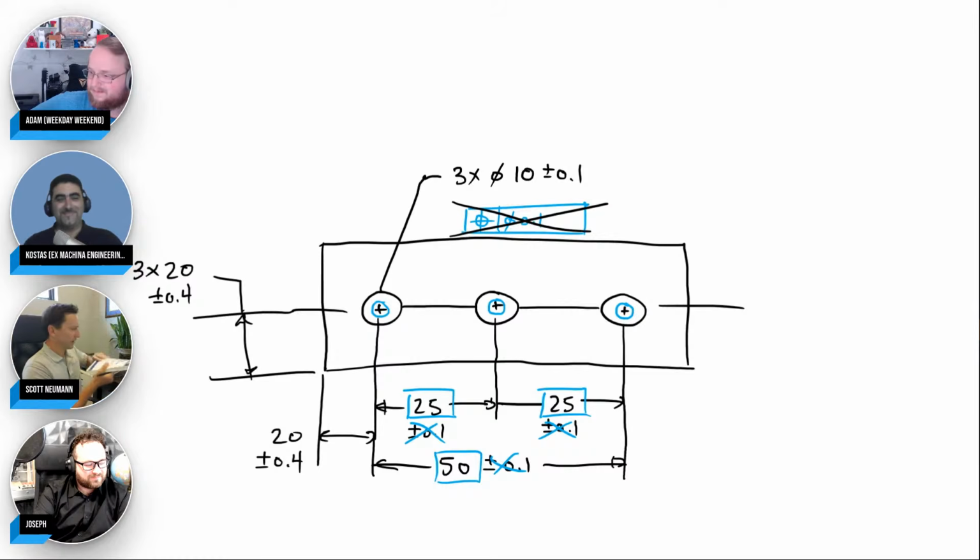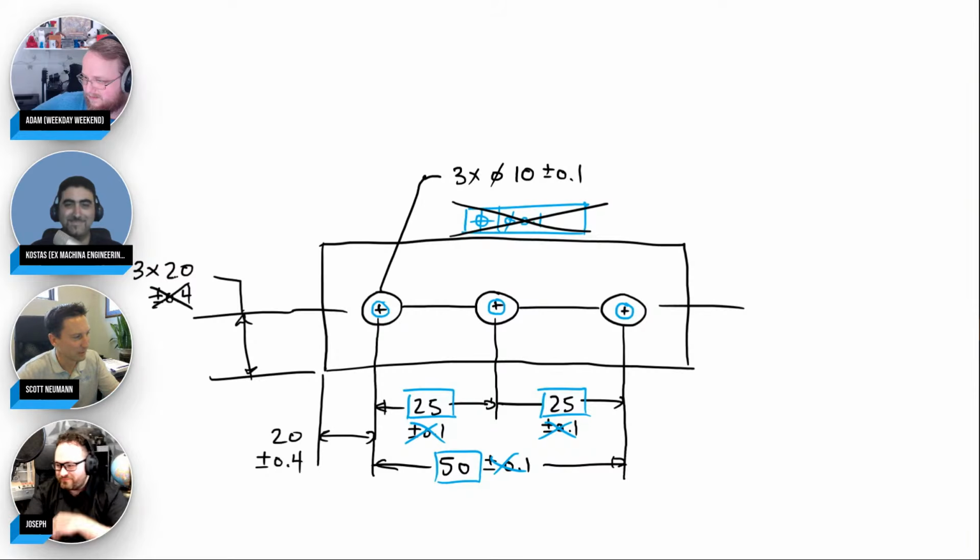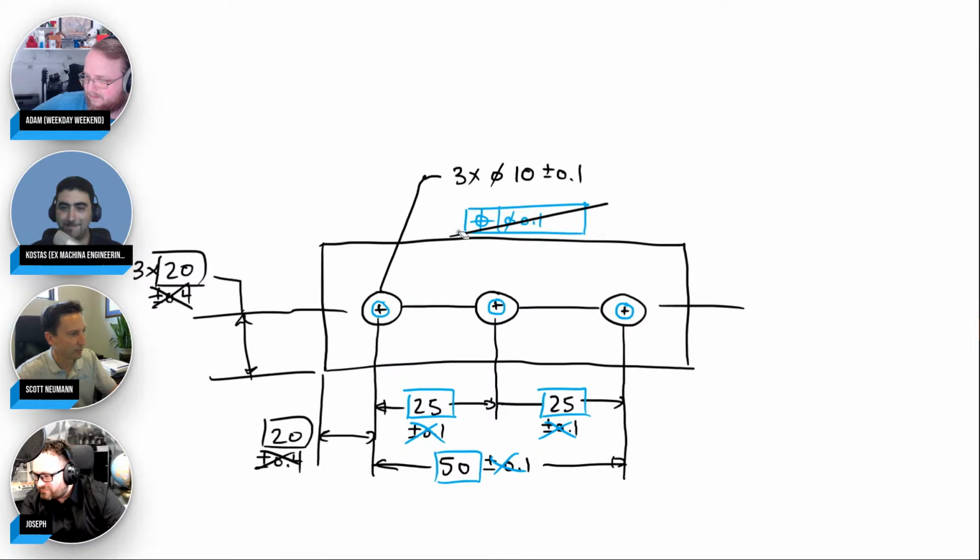So you go consult the standard, like, what does the dimensioning and tolerancing standard say about that? And the standard says, you're on your own, buddy. You're using a plus minus system that's unstandardizable. So that's why it's like, no, we don't do this anymore. We don't tolerance the dimensions. We make it all basic. Very true. No tolerance.